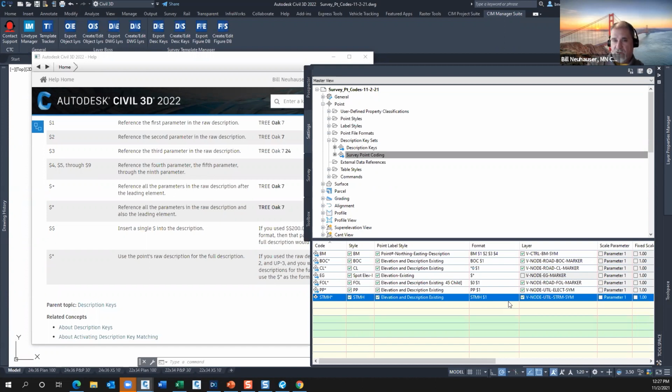If we put it on layer A, let's call this a group layer, okay? If I stick all of my manhole details, my utility manhole storm sewer details, all on one layer, layer A, now if I freeze layer A, I'm freezing just that group of details. I'm not touching my signs, I'm not touching my typical sections, whatever, just those manholes, okay? The third one is a unique layer, which they call layer B. Layer B is unique in that we can create a layer just for that particular detail, storm manhole detail number 5A, whatever, okay? So we have a layer just for that. So we get those three options, okay?